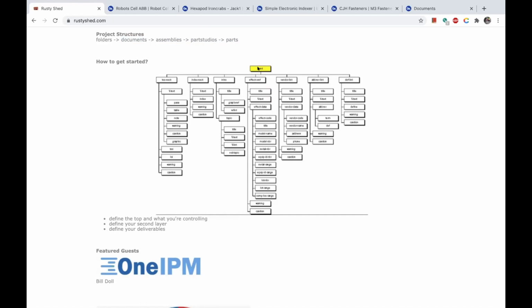So to me, I'm trying to define, I got a robot, I got to have the powered electronics associated with it. I would even go and say, okay, here's a rectangle, this is the room, and then I would actually map where the product goes through, and I would make those my datums. And then what I could do, these are my second layer assemblies. These are probably going to be the robotic cells, and I can pass the datum down into that cell, into this cell, into this cell. And now I've got all of these cells being controlled by my top layer.